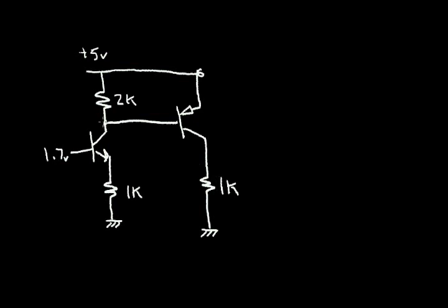Okay, now let me just point out a few things about NPN and PNP transistor schematics. Usually when we draw a schematic, we'll draw the positive power supply at the top, and ground will usually be at the bottom. And the emitter of the NPN will usually be towards the ground terminal, and the collector will be usually towards a higher voltage part.